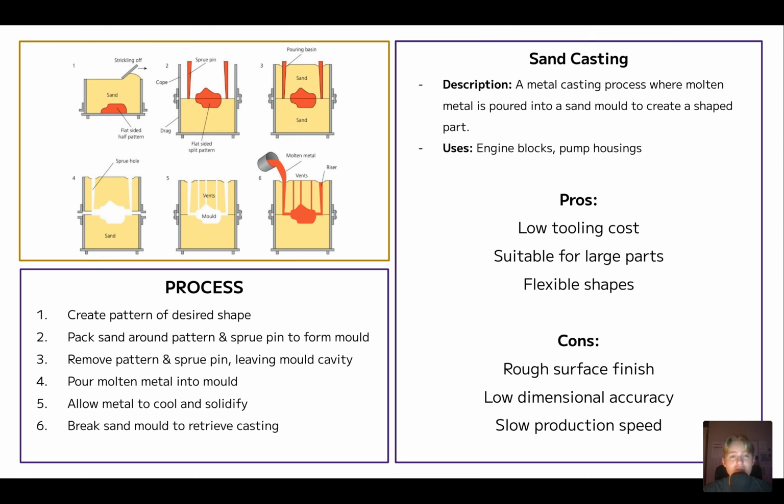And the cons of it would be that we create a rough surface finish because obviously it's sand. It's not going to create a smooth finish on the part, but that should be fine because, for things like engine blocks, you don't necessarily need a smooth surface finish on the exterior.